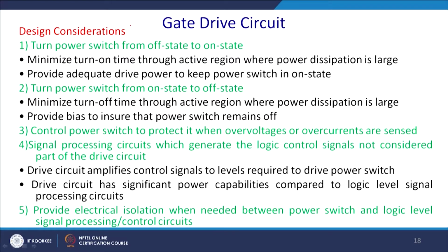So what does a gate driver circuit do? It turns on and turns off the switches. So these are the design considerations. Turn the power switch from off state to on state and vice versa. During transitions, power losses should be minimized, and any thermal heat generation should be evacuated.